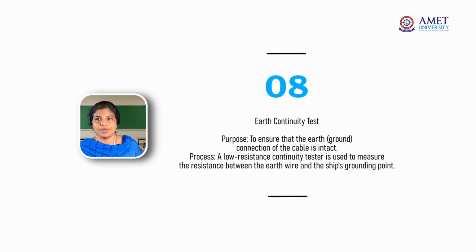Then the earth continuity test. In the earth continuity test, we pass a low current and measure the value of the resistance between the earth wire and the ship grounding point. Based on that, we can check whether the earth continuity is good or not.